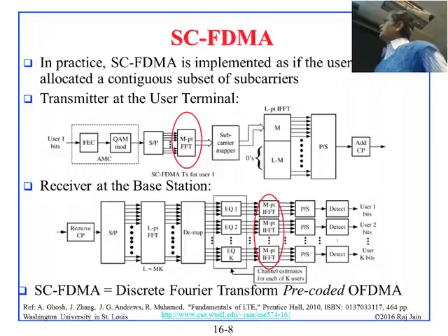And this is where things become different, and that's why I've ellipsed it. Now, instead of doing whole 1024 point IFFT, you take these things and you do a small FFT, and so this multi-carrier becomes, basically this becomes FFT, and now you put it contiguously here, M right there.